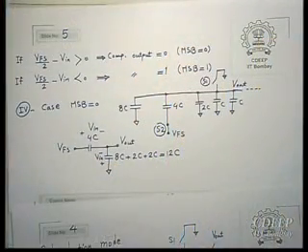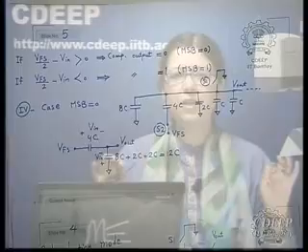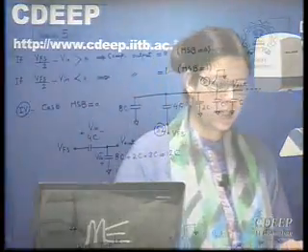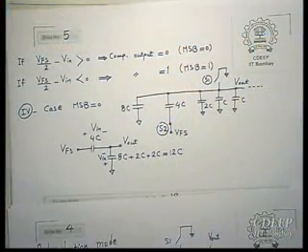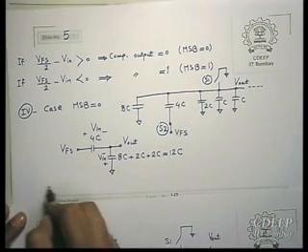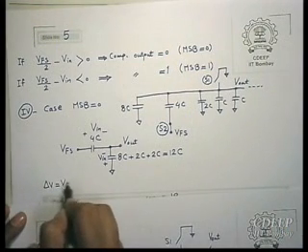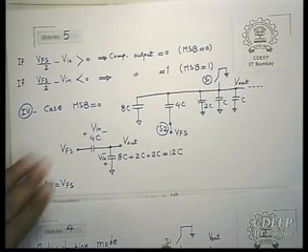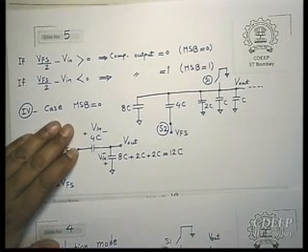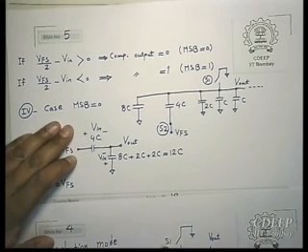So V in will remain as it is. It means that the sampled V in will always remain on the capacitors. So what will change only is the capacitive division. So again you have your delta V equal to V full scale. If this is open, this will be 0, or you can connect it to 0. Results will be the same.